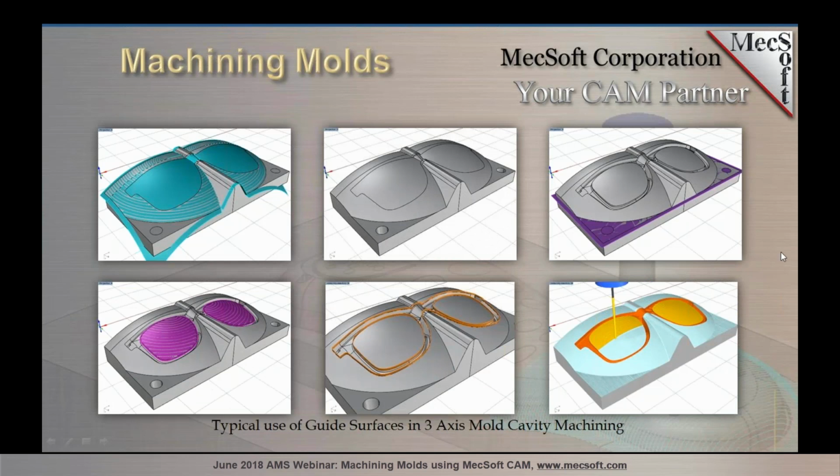Okay, what I wanted to show here was just some examples of some guide surfaces for the mold that Al showed us. And basically what you're looking to do is mask off the cavity. And not only to mask off the cavity, but also to extend past the insert boundaries so that you can get a clean cut past your insert. So here on the top left, you see a general masking surface that covers the entire cavity area as well as extends past the insert boundaries.